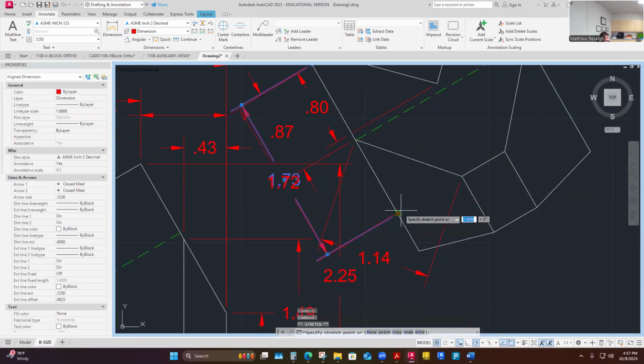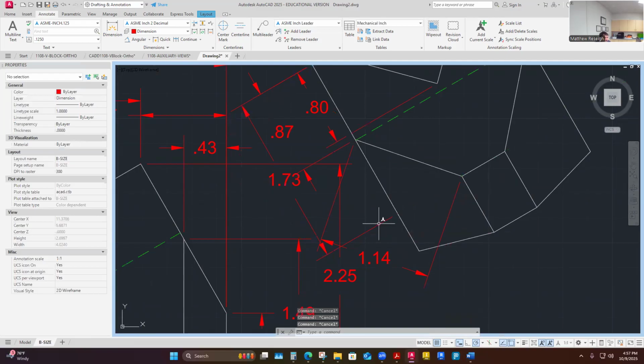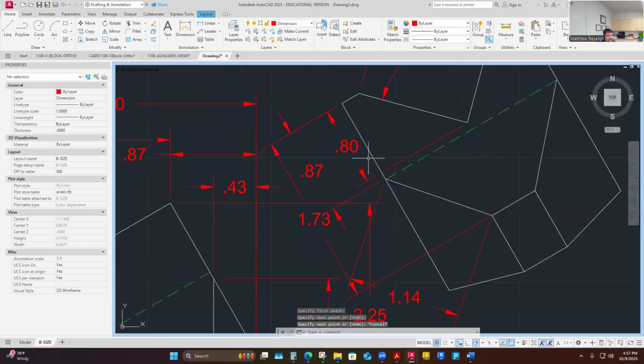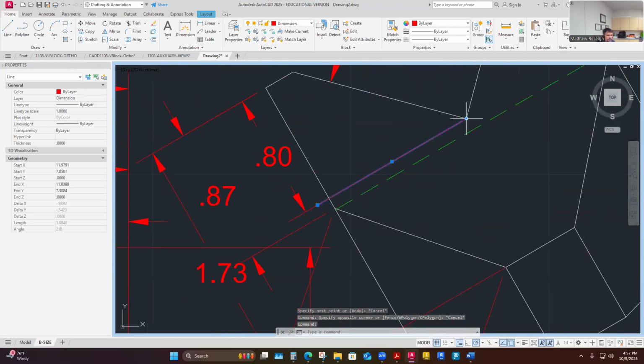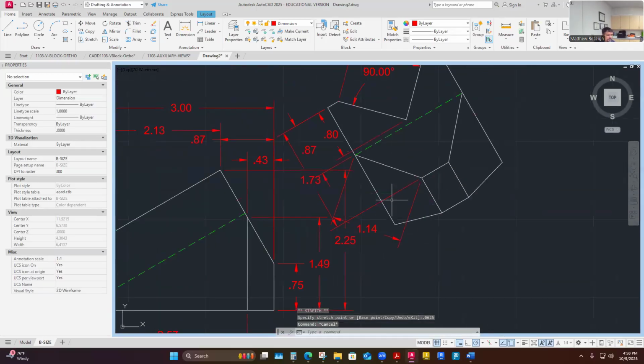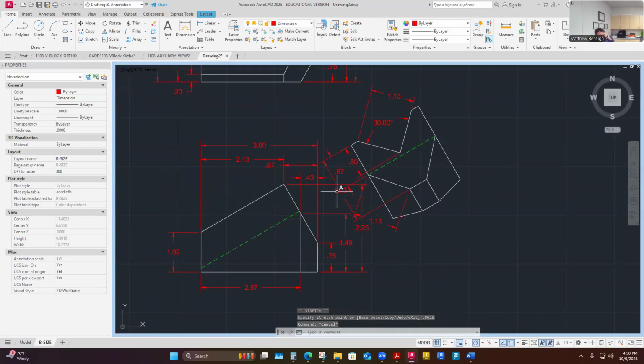And then what you'll notice with aligned dimensions, you can't just pull that over. It's going to do weird things, which is why I end up cheating with my lines that kind of become like that. So I cheat with these lines and I say, yeah, it's from here and it goes to there and that's great. And then really I break them away from what they're pulling from. So they end up looking on my drawing like extension lines, even though they're kind of hidden. Like that looks a little better. But this is an issue. This is why I have three.